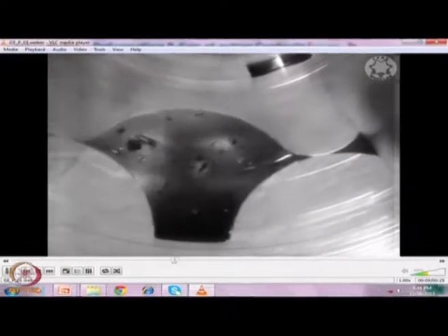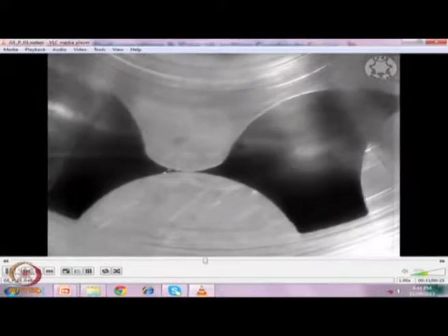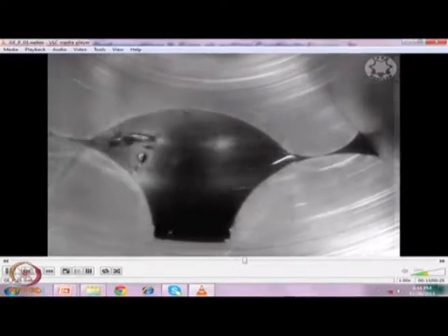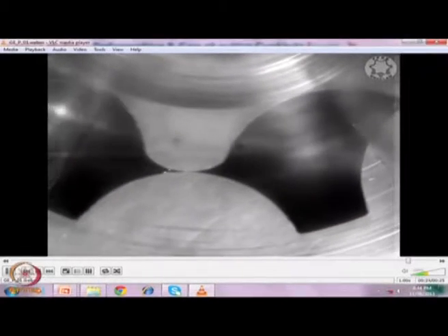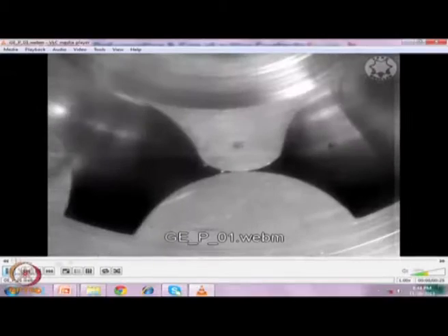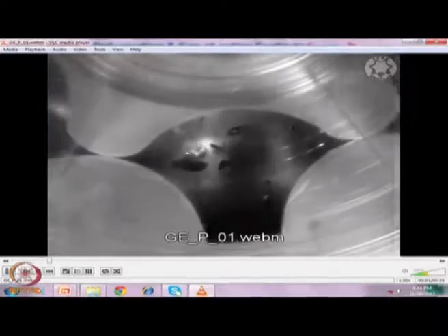What is happening if you look into this: when it is changing phase from the high pressure to the low pressure zone, this bubble is definitely where the leakage is occurring, that means the gap is occurring. So, what I have tried to prove theoretically is also happening practically. This is a good example of interchamber leakage.